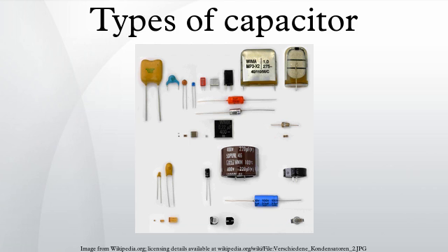Special capacitors. Printed circuit boards have metal conductive areas in different layers of a multi-layer board. Printed circuit boards can act as a highly stable capacitor. It is common industry practice to fill unused areas of one PCB layer with the ground conductor and another layer with the power conductor, forming a large distributed capacitor between the layers.